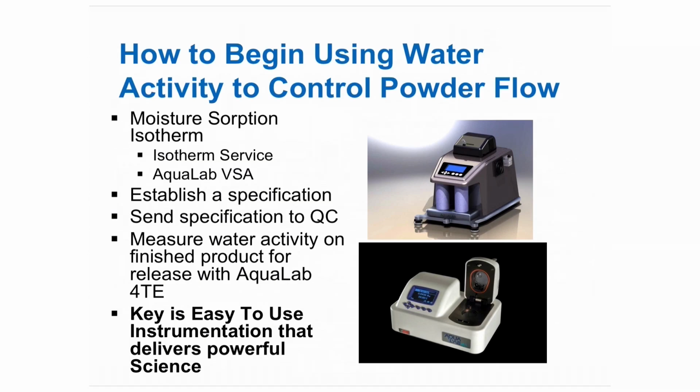Once you've done that, that allows you to establish a specification. You base that specification on worst case scenario conditions, and also on packaging. Packaging, of course, is something we didn't specifically talk about, but it certainly plays a role in all of this because it ultimately determines how quickly the water activity of a powder material changes when exposed to different conditions. But you measure the water activity of the product after it's manufactured using the easy-to-use water activity instrument in a QA/QC setting. Make sure that it's below the specification that's been set for stability. Once you've figured that out, you can go forward using that specification to track the stability of powders.